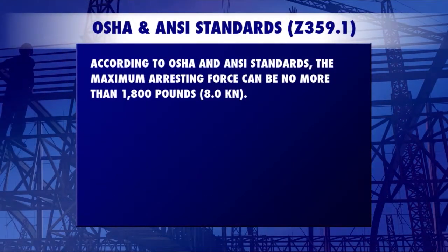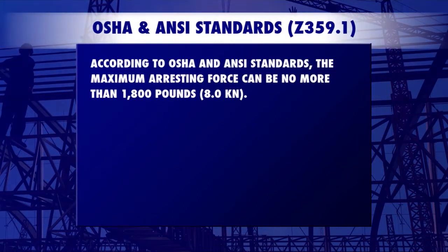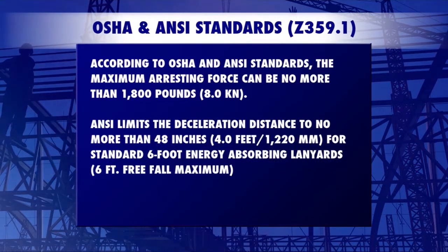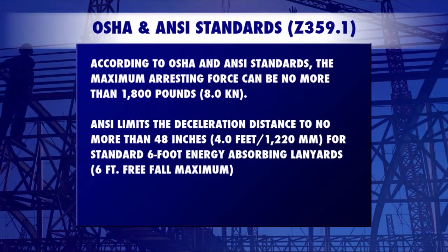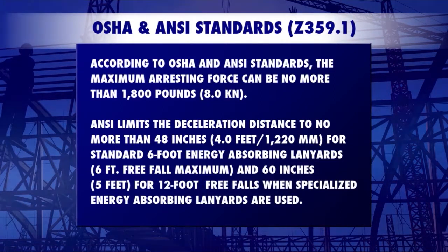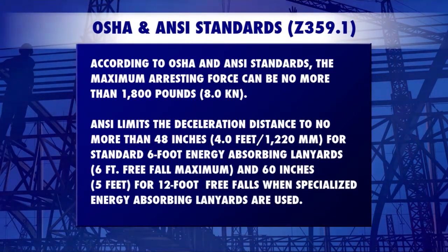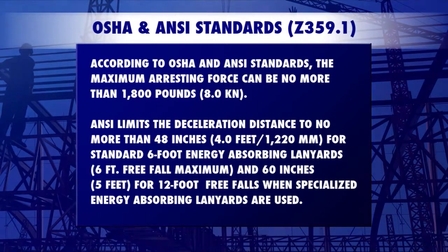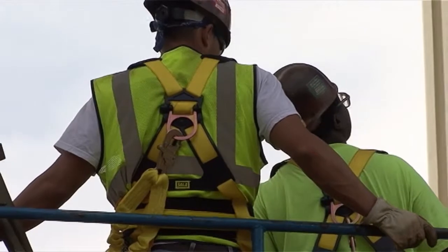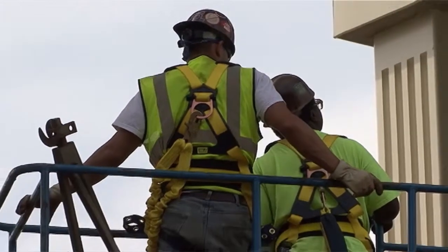According to OSHA and ANSI standards, the maximum arresting force can be no more than 1,800 pounds. ANSI limits the deceleration distance to no more than 48 inches for standard 6-foot energy-absorbing lanyards, and 60 inches for 12-foot free falls when specialized energy-absorbing lanyards are used. We'll discuss deceleration distances in more detail in just a few moments.